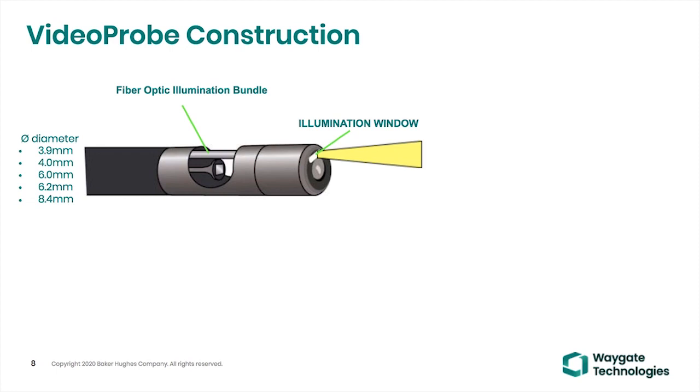you have to have light. So it comes to a fiber optic bundle. It goes through the optical tip adapters and shines on the scene. So that the scene can then be illuminated and the light come back into your CCD imager. Okay, so lighting and imaging, great, but that's not the whole story.